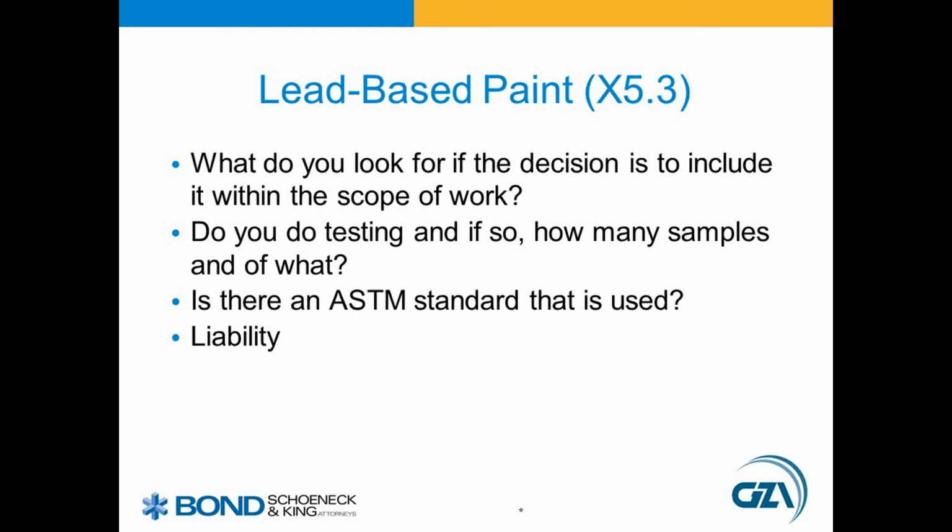Housing and Urban Development revised their guidance in 1997. In that guidance, they suggest different frequencies of sampling. It depends on what the object is you're sampling. It goes as far as door versus windowsill, that sort of detail, and that guidance can be very useful in determining what you need to sample and how much of it. Obviously, if you have an old building, there are probably multiple layers of paint, and so each layer of paint would need to be tested individually.